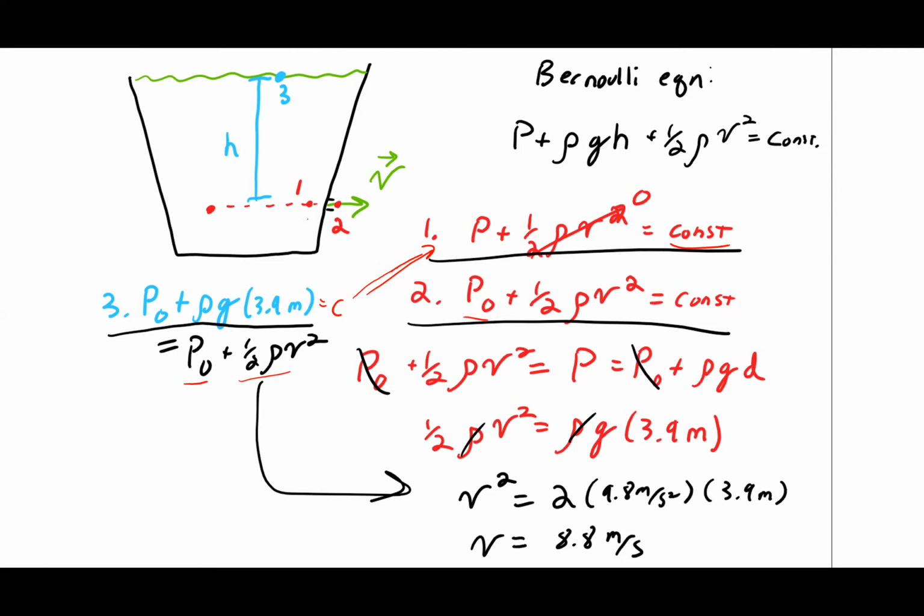So what we have here, just like with the hose problem, is a bigger pressure over here, and then just atmospheric pressure on the outside of the bucket. And just like with the nozzle, it's that difference in pressure that's going to act to speed up the water. So the fact that there's a velocity of water coming out of the bucket while water inside the bucket is relatively stationary comes down to the work being done by that difference in pressure at the hole.